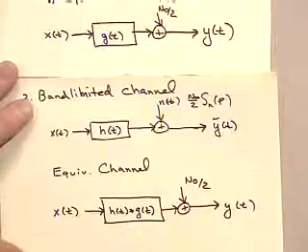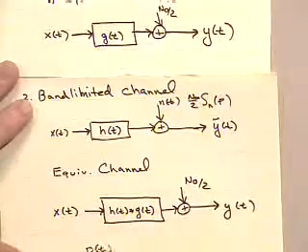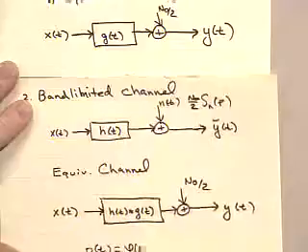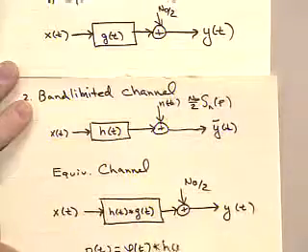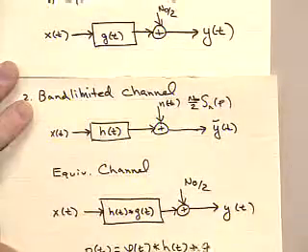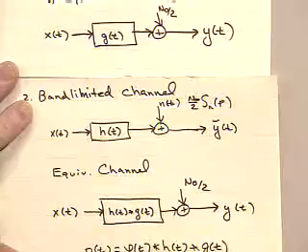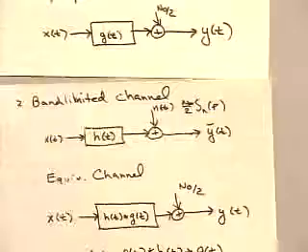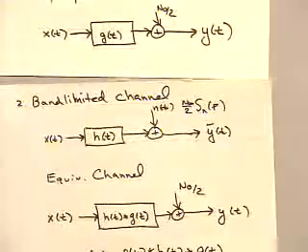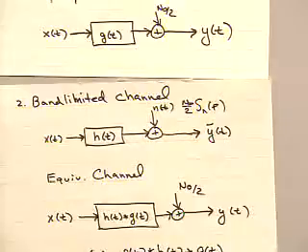And if I know the basis function, then my p of t in this case would be phi of t convolved with h of t convolved with g of t. And I have p, then I can go to q of t, and I can characterize that channel in terms of intersymbol interference. Okay? So the trick in dealing with correlated noise is simply to run it through a whitening filter, and we can treat it like ISI.